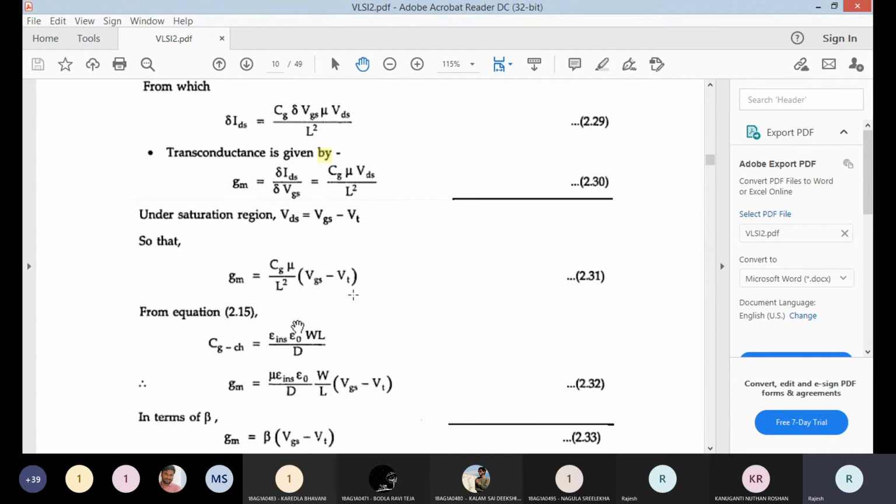You get this equation. So all these equations are useful for small problems in Part A if it is in your syllabus, or objective mid-exam bits, or in your GATE related exams. Wherever you require MOSFET characteristics, you require all these parameters. GM is proportional to VDS, inversely proportional to L square.